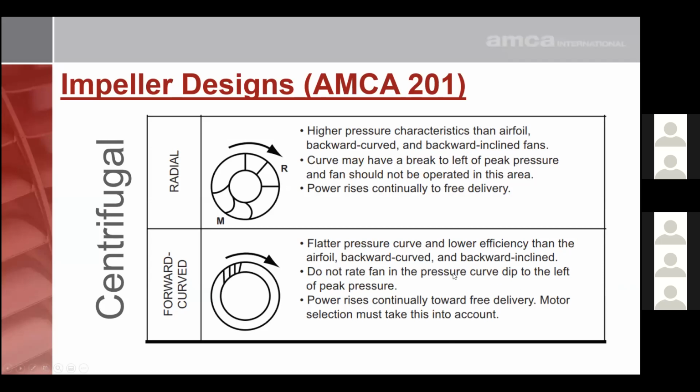And then forward curved fans. They're not so common anymore in industrial applications. They're more common in furnace fans, that sort of thing. But in the past, they were used for induced draft applications because they do provide a high flow at a low pressure, they have a slow operating speed, and they're fairly quiet. So they still have many good uses.